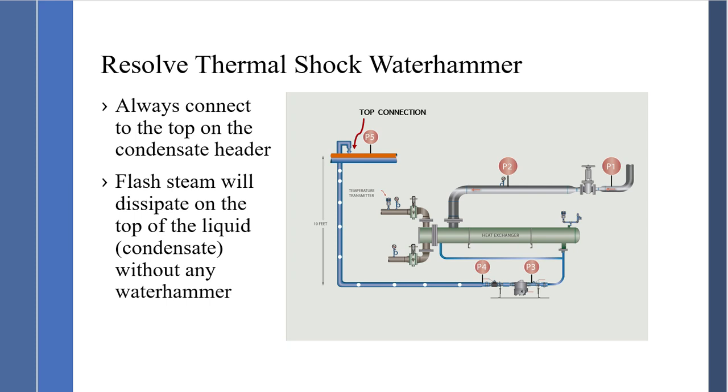To resolve thermal shock or Waterhammer, always connect to the top of the condensate header, as shown right here. Even if the condensate line is totally filled with condensate, the flash will dissipate on top of the water or condensate without any noise effect. So in condensate systems, the connection always has to be to the top, never the side or the bottom. And that will resolve the thermal shock or Waterhammer.